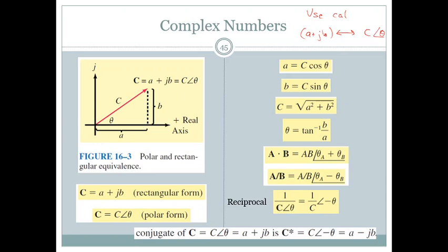So you can use the calculator, but keep in mind, when you are entering a value in the calculator, it will actually be i that you have in the calculator, and we have to enter it as A plus 5i, something like that, not i5. But in mathematical representation in electrical analysis, we will always be putting the j in front. Keep that also in mind.